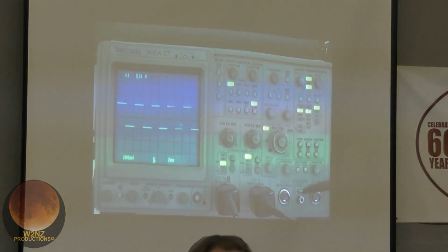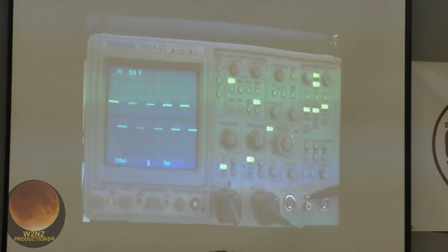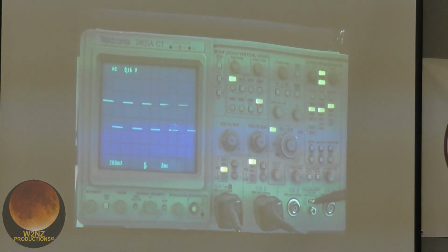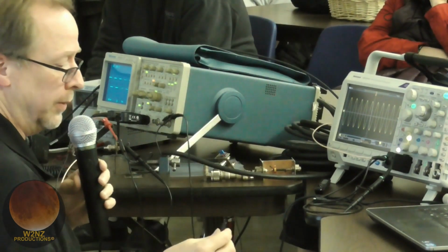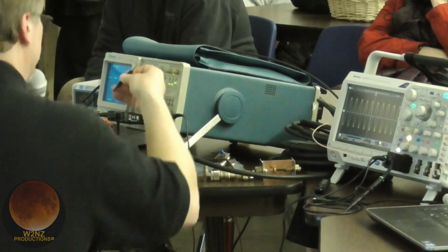And remember, a square wave has energy at essentially the fundamental frequency of the square wave itself, but also has energy at higher frequency content, at odd harmonics. And that's what makes the edges fast. The more high frequency content there is, the faster the edges. So even this 1 kilohertz square wave has content out to hundreds of kilohertz or more. But this probe is properly adjusted.